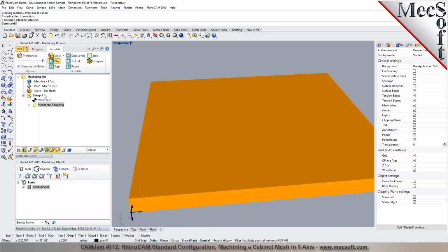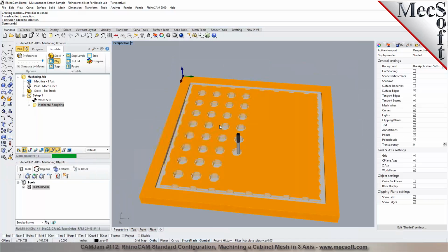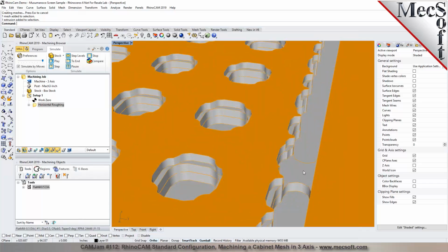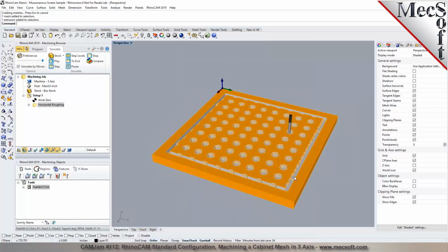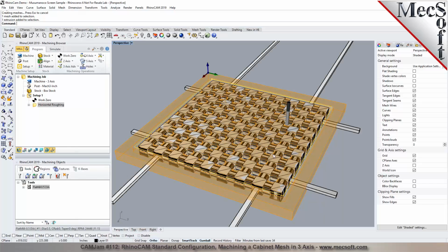And let's go ahead and do a simulation. And you can pause and go all the way to the end. Okay, so you see the tabs here? Yeah, they're still there. Yep. Cool. So you've got two tabs on each side. Okay, and you can obviously control, when you create your solid box, you can offset it if you wanted exactly a certain distance away from the center line or whatever. Okay, so there's our roughing operation. And we've got tabs in each of the corners.